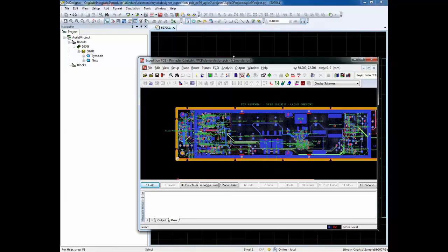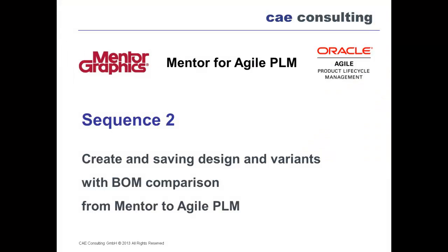It must be said that Integrate To supports several options for design creation. For example, there are different options or workflows. For example, the design engineer can create a design where there is nothing yet in PLM. Alternatively, some items must pre-exist in PLM, like assembly items. Another possible flow is that the design is only started with a schematic and then the PCB is subsequently added to the design. Okay, this concludes the new project creation process.